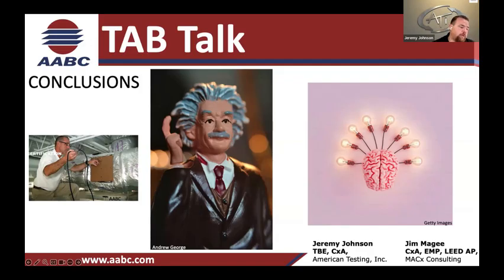The system was full of air. The system was full of debris. Getting the place to a system where we balanced it took 4 passes through the system, 20% of the system had to be checked, and the repeatability had to be within 5%. That's my story for the day. But that was an extreme situation where the commissioning guy had to come in as we were doing it, because from a time and efficiency standpoint, it was the right move to make.